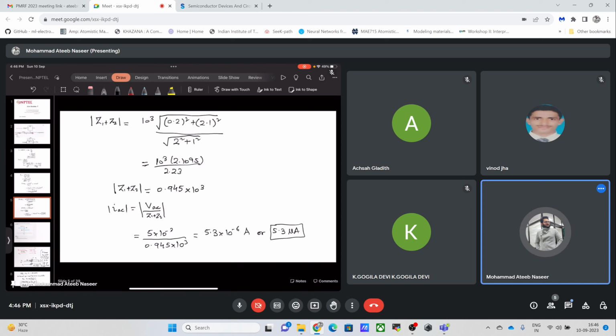That's what I was trying to say when we were drawing those PN junctions, how the electric field at the interface would be a function of x. Would it be x, x square, would it be constant? For that I had told you to find the electric field, and you knew that the electric field would be constant in that case because the concentration was constant, as a result of which the field came out to be a linear function of x, and the potential, or the energy band bending, came out to be a quadratic function of x.